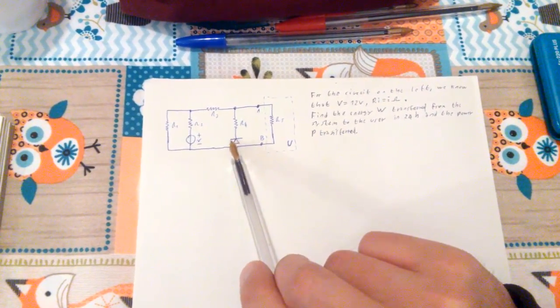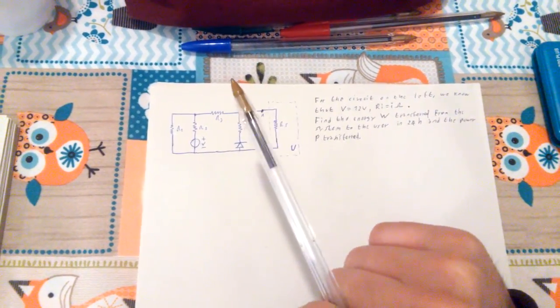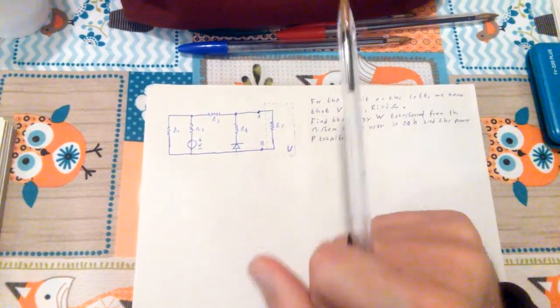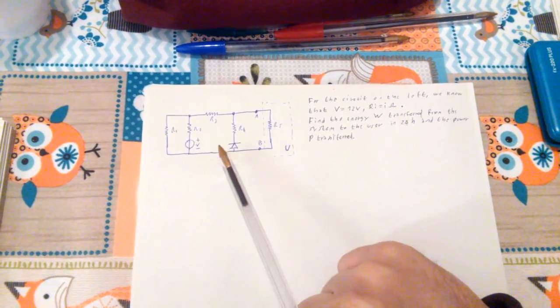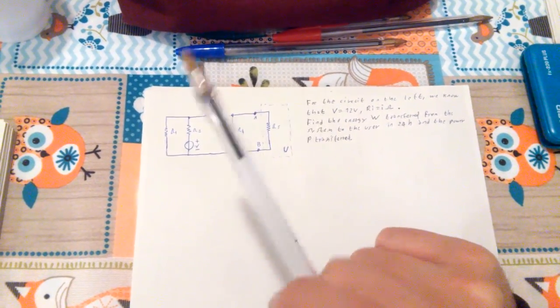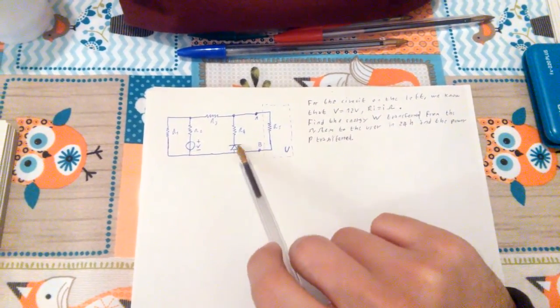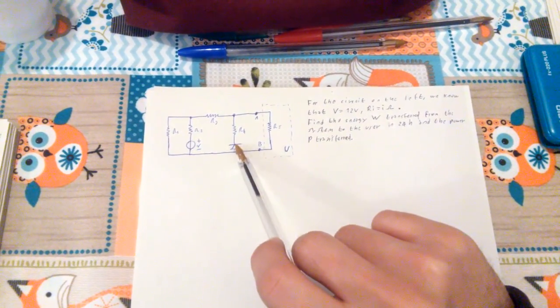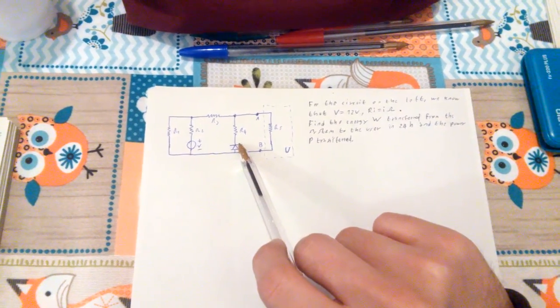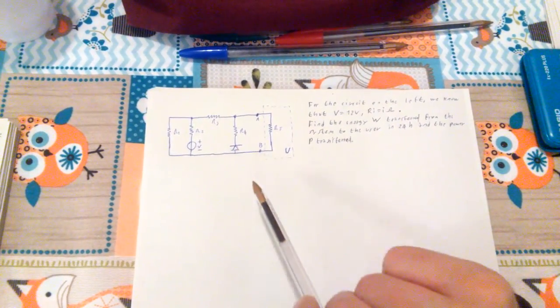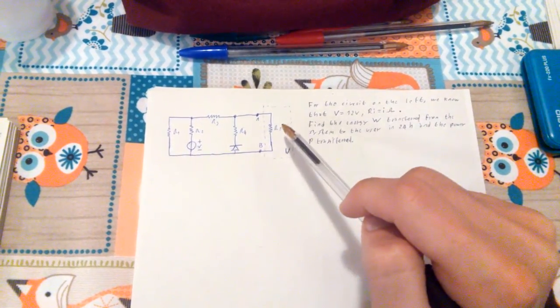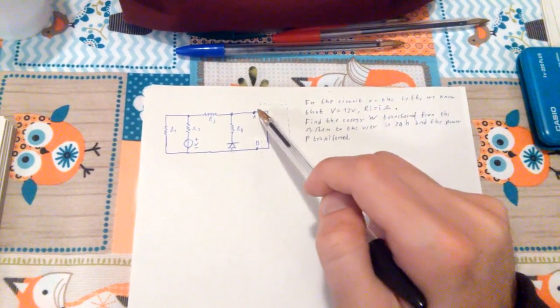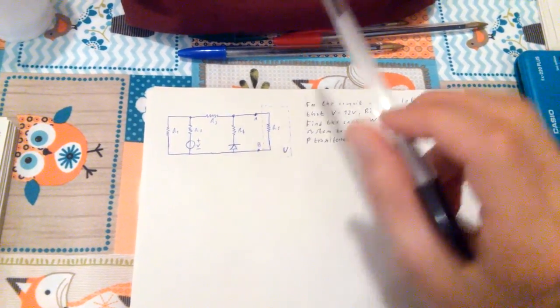So I can actually do 2 things before trying to find the Thevenin equivalent circuit. I'm going to redraw this circuit and swap this diode with an open circuit, because current is not going to flow through here. It's an ideal diode. And I'm going to make it end across A and B.